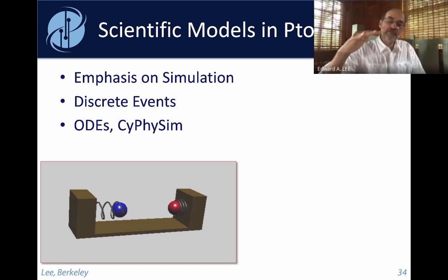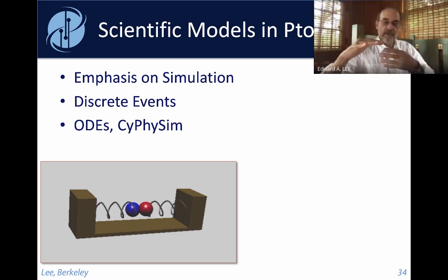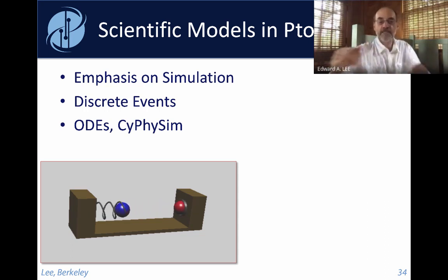is it's a microelectromechanical system where you float silicon fingers that are suspended above the chip and that bend when the chip accelerates. And then you measure capacitance because the bending moves the position of the silicon fingers and changes the distance between two capacitive plates.